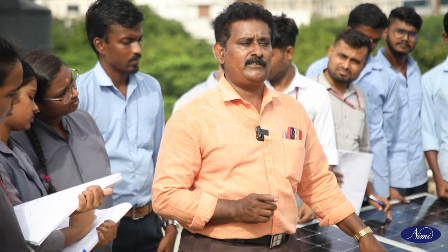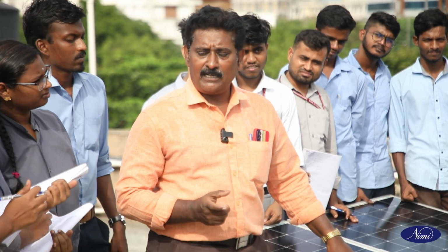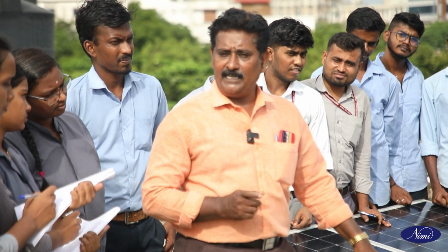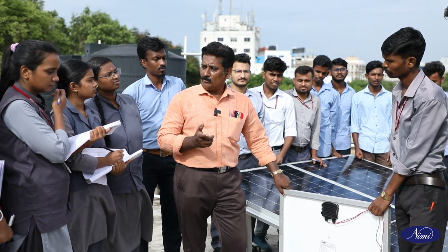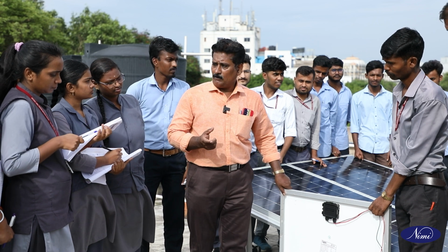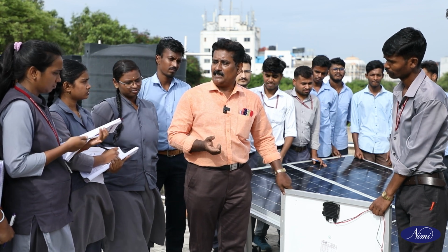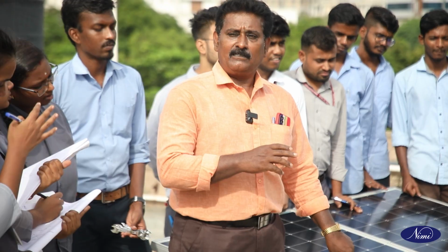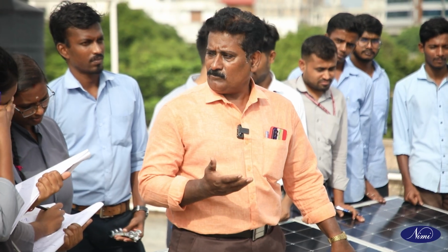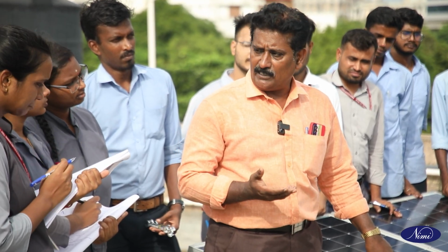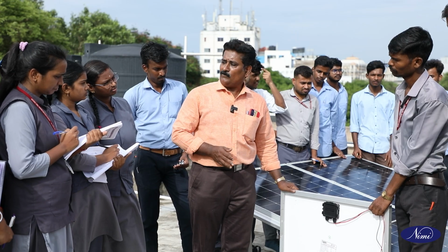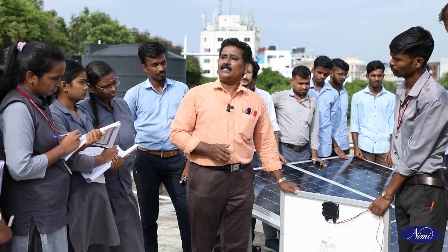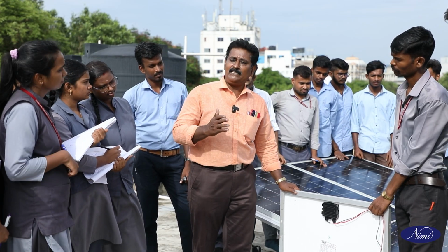We have to check the specifications of various solar panels. From the nameplate details, only then will we get the idea which panel has more efficiency, or which panel is made of polycrystalline, monocrystalline or thin film. Then which panel has the maximum system voltage or open circuit voltage, and which panel has the higher short circuit current, that we can see from the nameplate details. For that we have to compare the various panels.